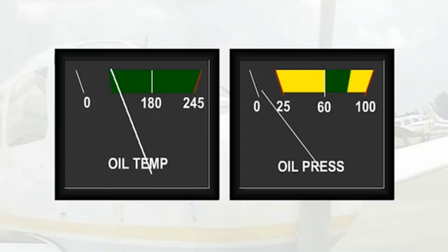After engine start, the oil pressure must be indicated within a specified time. If the engine is started from cold, then the oil pressure may initially seem excessively high. However, as long as the oil pressure drops to normal as the engine warms up, this can be considered acceptable.